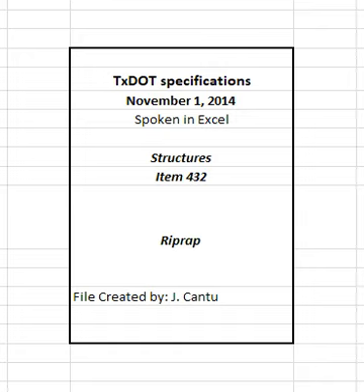Provide stone that, when tested in accordance with TxDOT 411A, has weight loss of no more than 18% after 5 cycles of magnesium sulfate solution. Perform a size verification test on the first 5,000 square yard of finished riprap stone for all types of stone riprap at a location determined by the engineer.